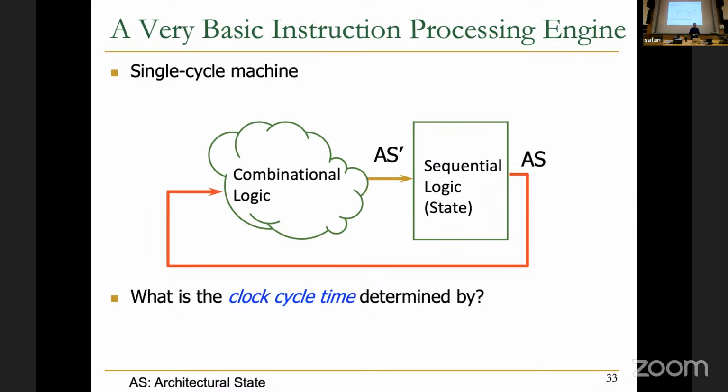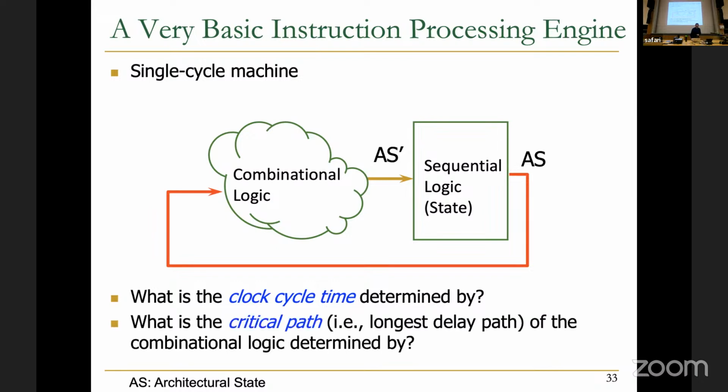That's true, but what is that determined by? Okay, you go ahead. You can say it that way, yes, but I would rephrase it. I think you're going in the right direction, the longest instruction to execute, basically. The longest instruction to execute determines the clock cycle time over here. The answer to the first question is critical path, as you guys have guessed.